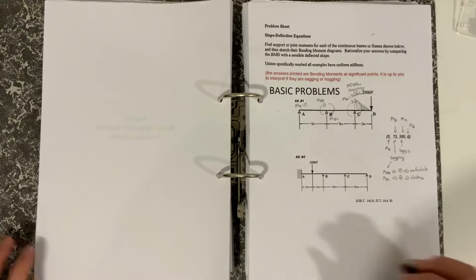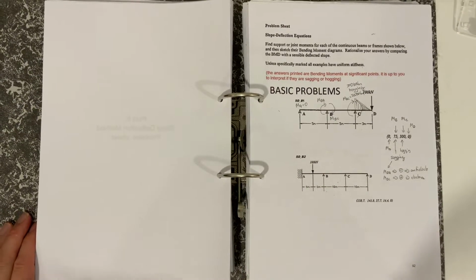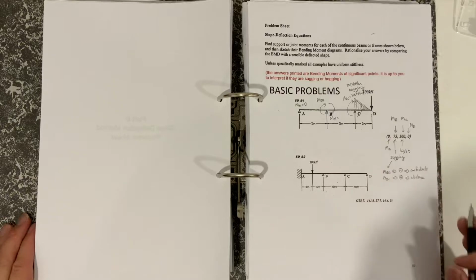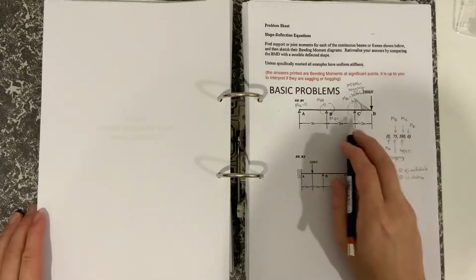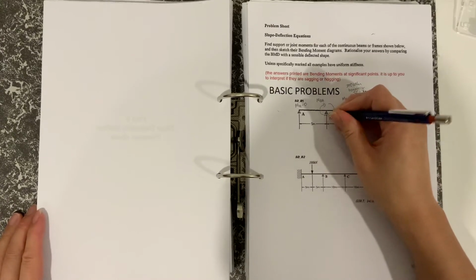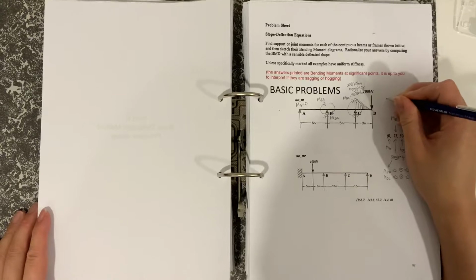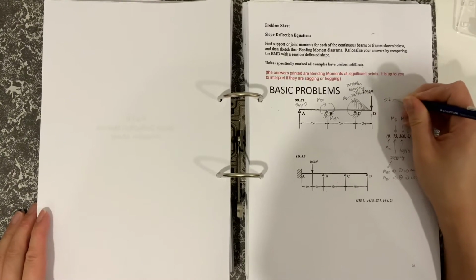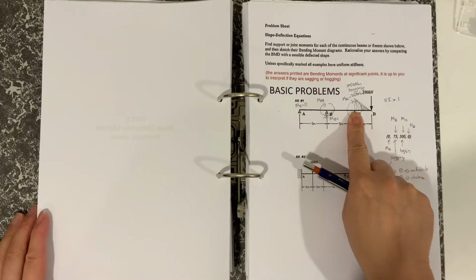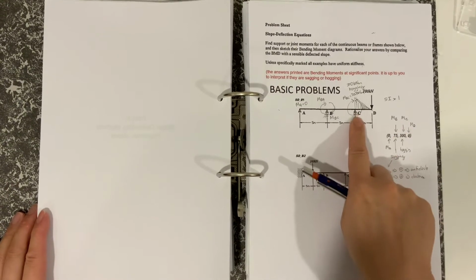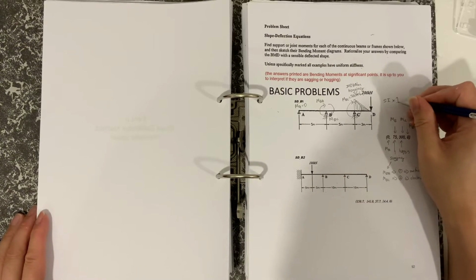Okay, and from there, once you've got that, you would be able to work out the reactions of the statically indeterminate structure. Actually, on this one, technically speaking, these should be pin and roller, and this one here would be statically indeterminate by 1, since if you remove that one, it would be statically determinate. So this is the one unknown, so statically indeterminate by 1.